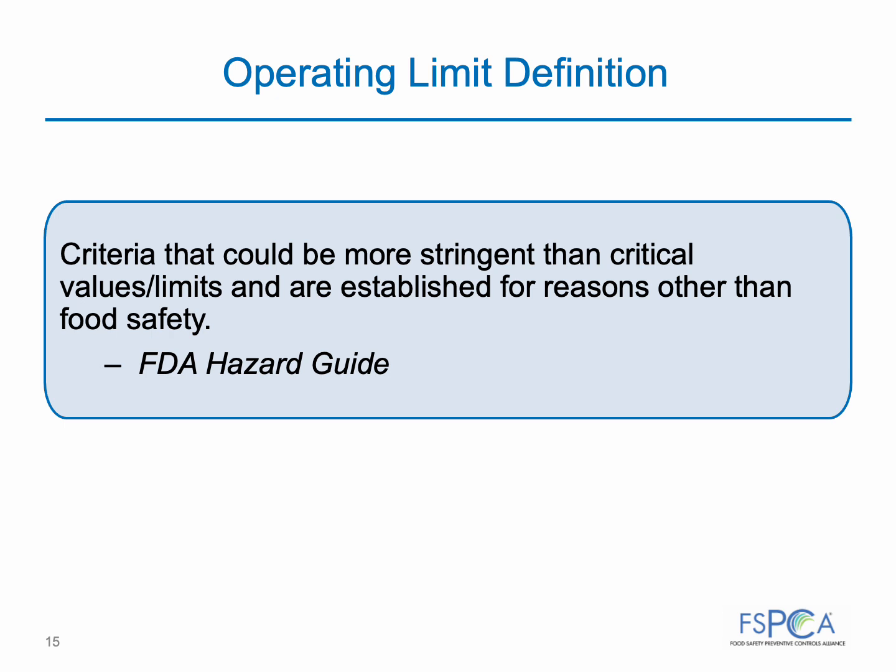A process may be adjusted when the operating limit is not met, which avoids deviating from the critical limit. These actions are called process adjustments. A processor may use these adjustments to avoid loss of a critical limit control, resulting in a process deviation and the subsequent requirement to take corrective action. Spotting a processing trend toward loss of control early and acting on it can save product rework or, worse yet, product destruction.